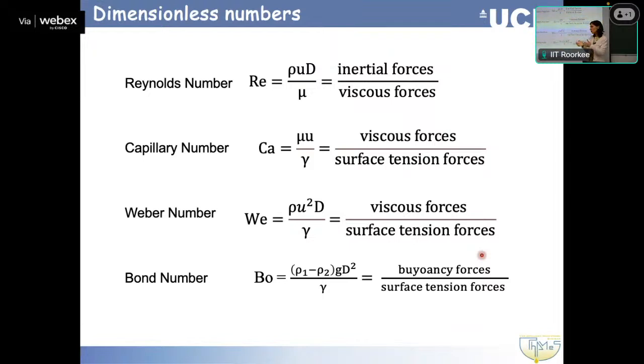And when you go to two-phase flow papers in microchannels or in large channels, it's good to pay attention to how exactly they have calculated the Reynolds number, because the way they implement the definitions can vary, especially these parameters, the velocity, and sometimes maybe the characteristic diameter here. And with capillary numbers as well. And again, if you have two phases, you can define them either from one or from the other, or from both. Give them both.